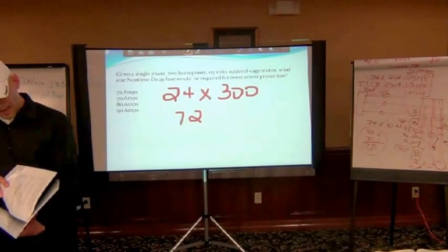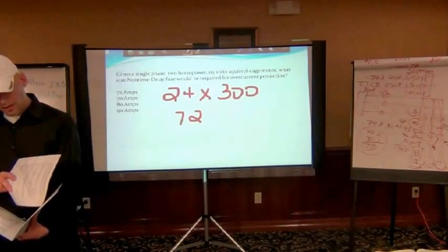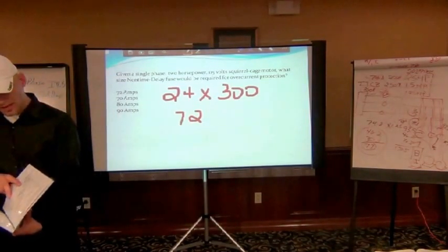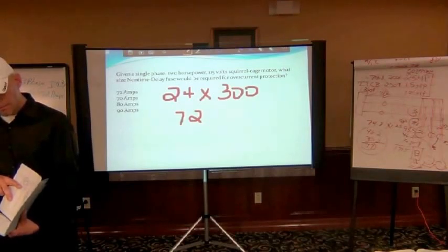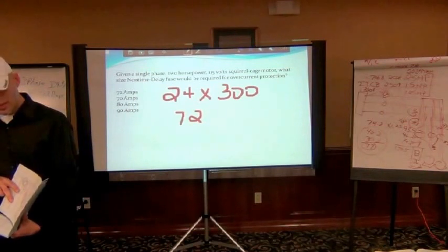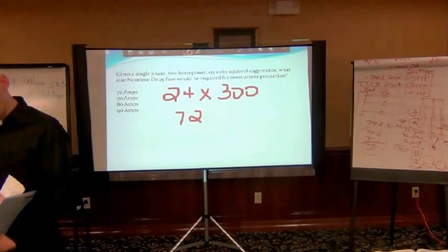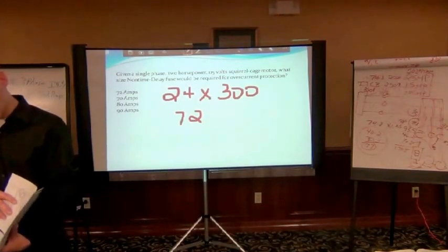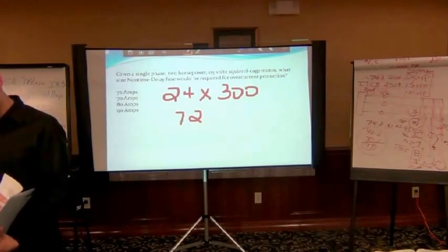Each one of them has a tap that's 23.5 feet away. This is almost exact word for word, guys. Set of feeders, 480 volt three-phase, all of them. You had a 25 horsepower short time duty, 15-minute rated motor, which, guys, doesn't have anything to do with sizing, well, it does have to do with sizing wire for a feeder, so I have to leave that in there.